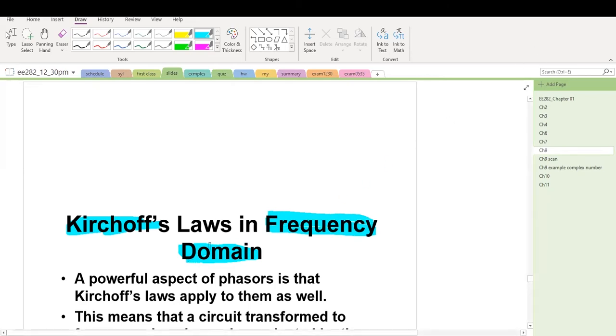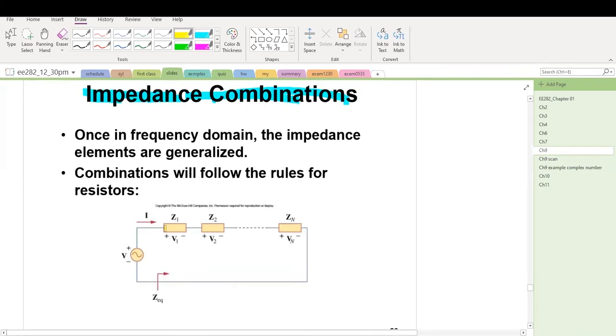We know the strategy of Kirchhoff's law, meaning KCL and KVL. We can use the same strategy to analyze AC circuits where sinusoids are involved. We use a small rectangle to represent any element in the phasor domain. This element can be a resistor, inductor, or capacitor.